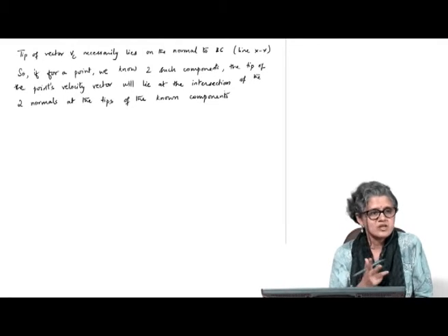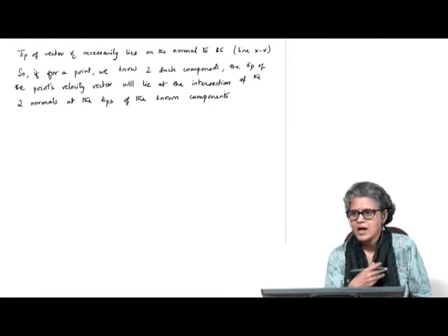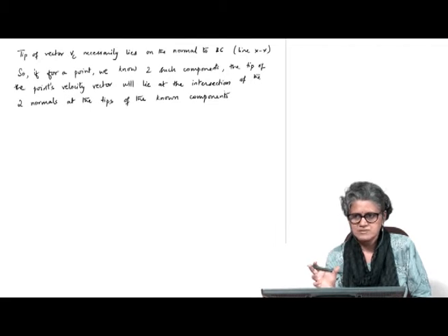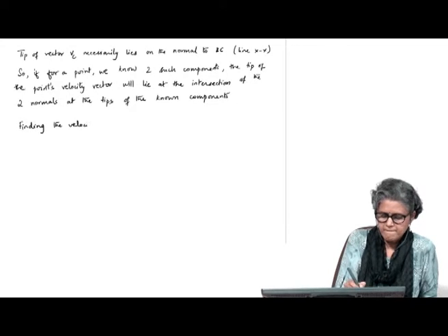So if I can find the velocity of two such points on a link, then I know everything about the velocity of that link, because if I find the difference, then I know the omega of that link. So if you know the velocity of two such points, let me just draw the two links, or we'll do an example actually.